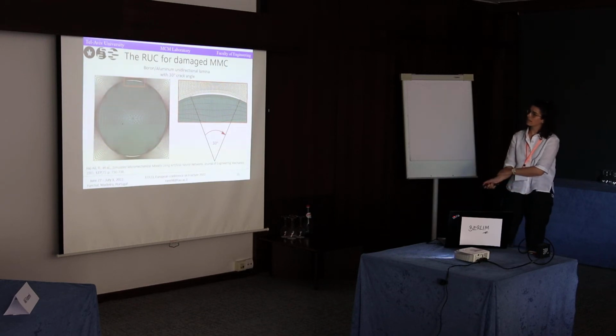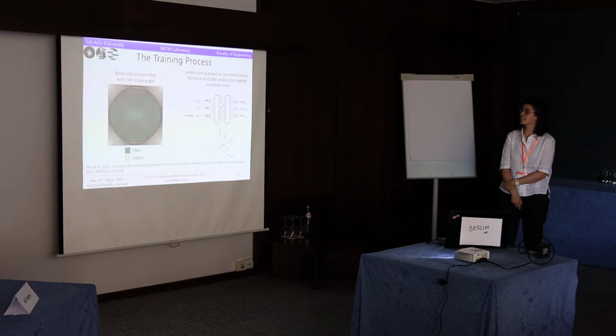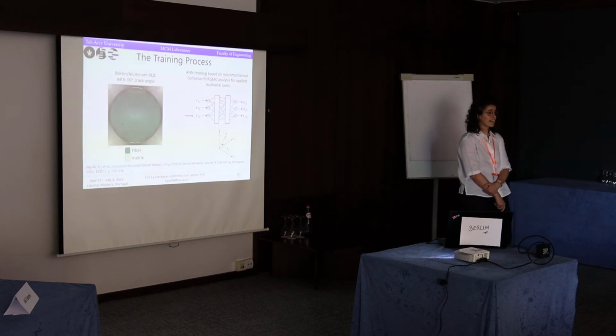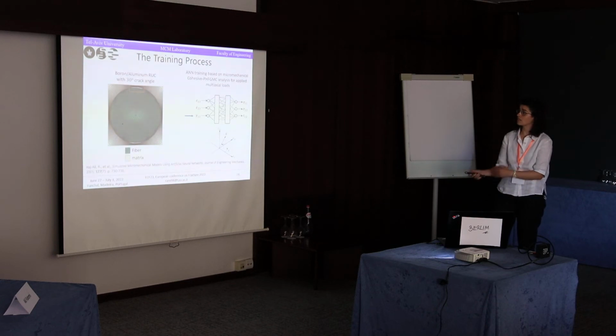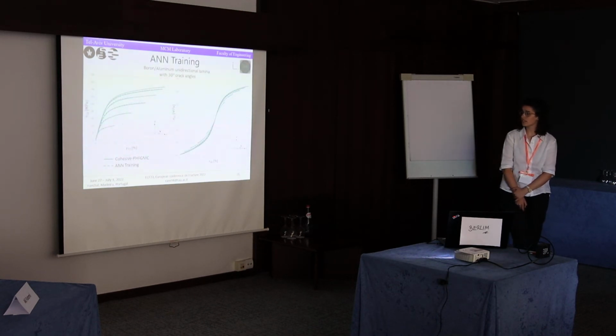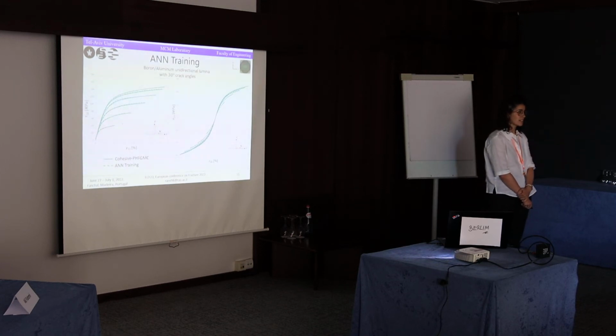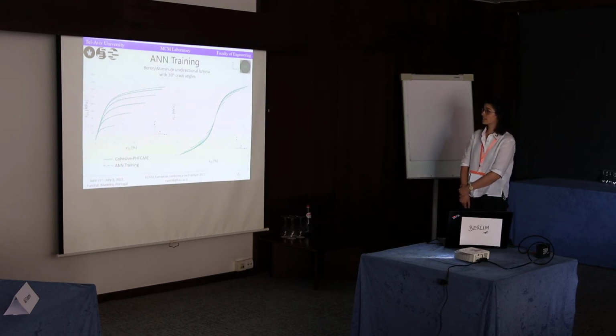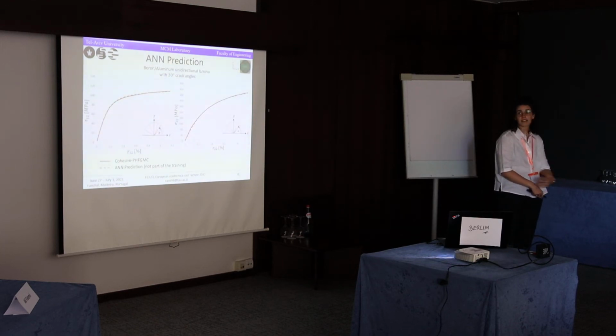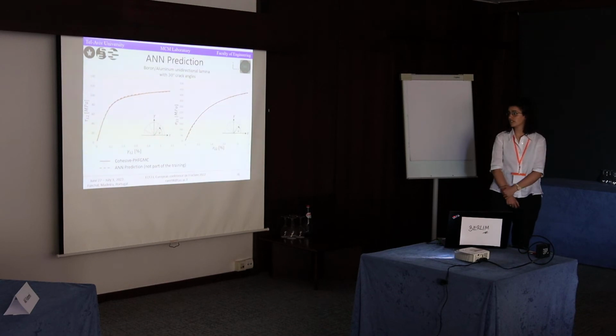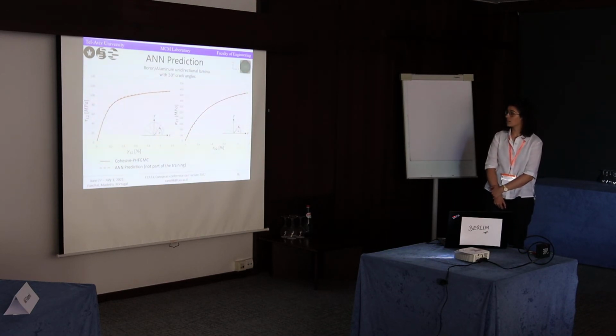And again, we trained the ANN based on this RUC multi-axial applied loads, again under the assumption of plane stress. We took the strains for the inputs and the stresses for the outputs. And here you can see the results of the transverse and the shear responses for the training compared to the cohesive PHF-GMC simulations. And after the training is done, the parameters are set, and we can predict. We can see the prediction of the ANN for a strain test that was not learned before.